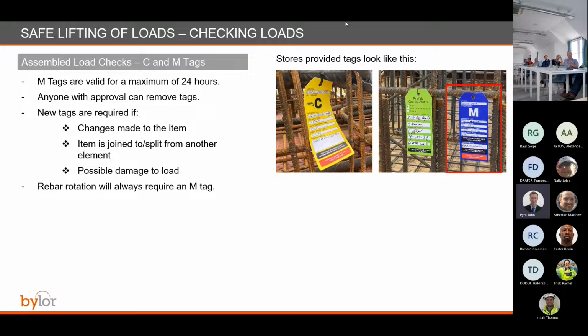And on that, it's got who's signed it off, say it's okay for lifting, the date, how long the tag's valid for, any relevant information about the drawing, so we can go back and double check the lifting points, and any other useful information for it.